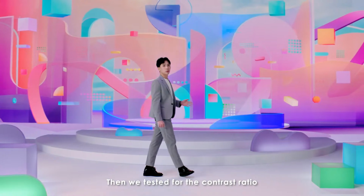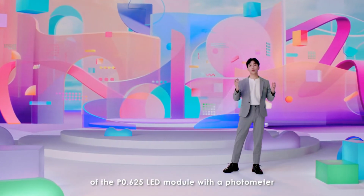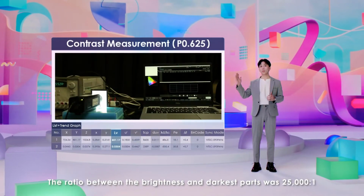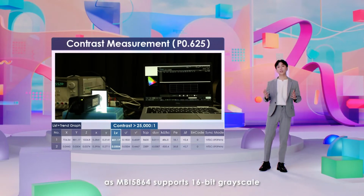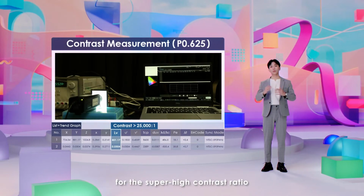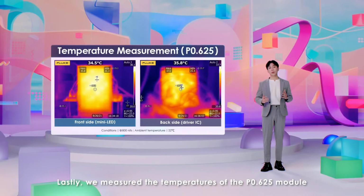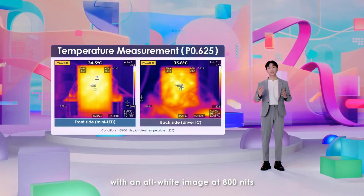Then we tested for the contrast ratio of the P0.625 LED module with a photometer. The ratio between the brightness and darkness parts was 25,000 to 1, as MBI 5864 supports 16-bit grayscale for the super high contrast ratio.